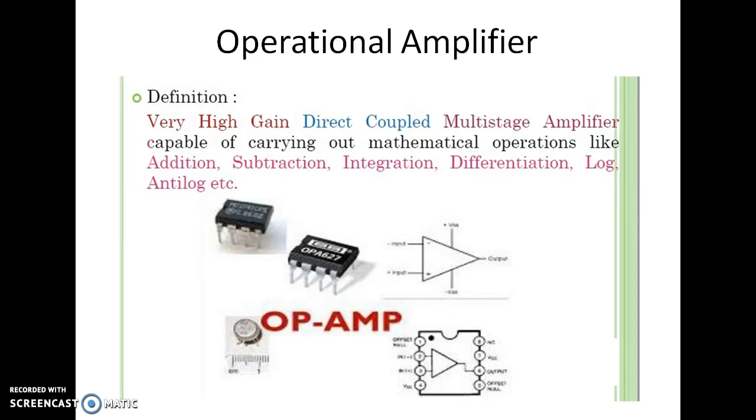Op-amp is basically a multi-stage amplifier which uses a number of amplifier stages which are interconnected to each other in a complicated manner. These internal amplifiers are transistors or FET as an amplifying devices. All this internal circuit with many transistors, FETs, resistors will occupy a space equivalent to pin head. The integrated op-amps has the advantages over the conventional amplifier as small size, high reliability, reduced cost, consumes less power.